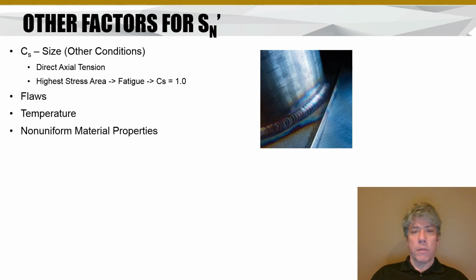I was just watching a video the other day because I bought some I-beams about how to straighten structural steel. And there's a process called flame straightening where you purposely heat up material. That material deforms and you end up with all kinds of fairly complicated stress distributions within the material, tension and compression, that affect the material's properties.